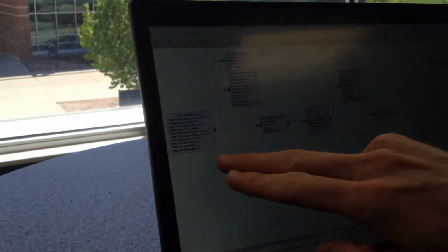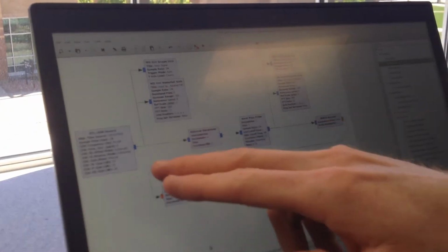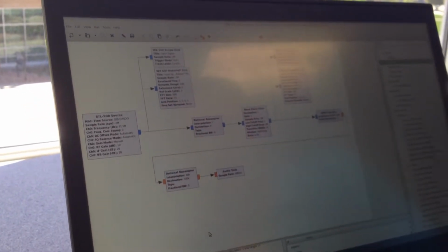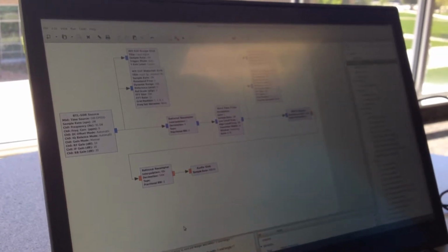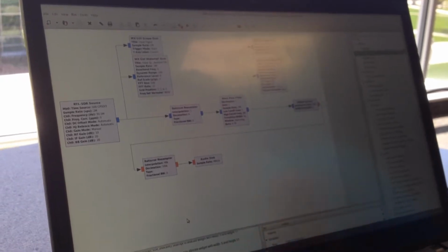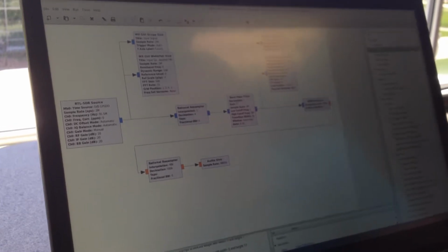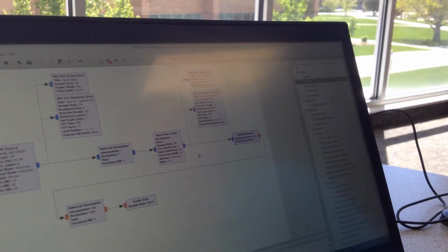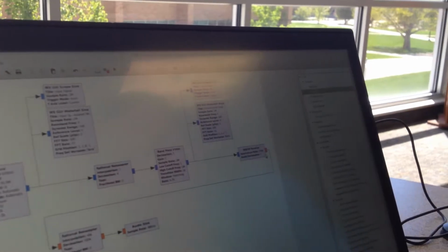So this is my block diagram. The first thing that I do is I read in the signal from the antenna, then I resample that signal, and back here I demodulate that signal to the radio frequency that I would like to listen to, and put it essentially at baseband, at 0 frequency. That's the one I'll be viewing. Here I can filter it. This is a band pass filter, so it'll cut off low frequencies and high frequencies based on the setting that I give it.